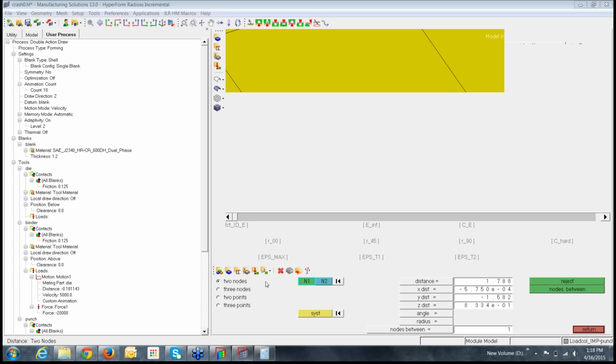Not necessary, Danish. Only the blank thickness should be more than sufficient for you. Strength factor is meant for blank only, not for your punches. Adaptivity is division of elements in the regions where it needs to capture those features. It gets divided only for the blank, not for the tools.